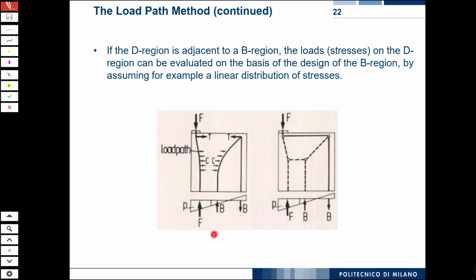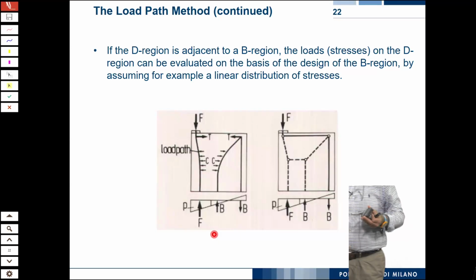Each one of them worsens the other. Yes, because if you have a very high axial force, you have to engage a larger part of the cross section just to carry the axial force, and you have a narrower part to carry the bending moment. That is the way in which you can also see the interaction between axial force and bending moment.